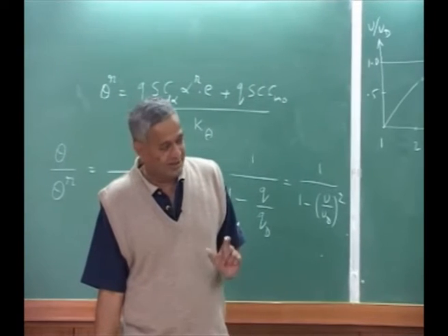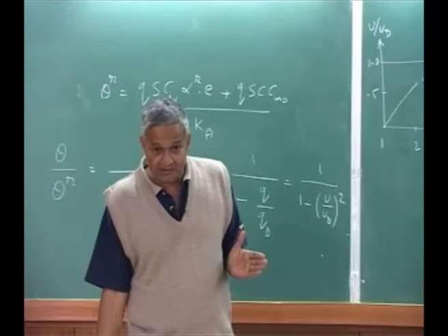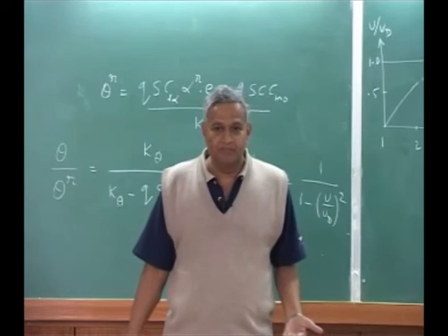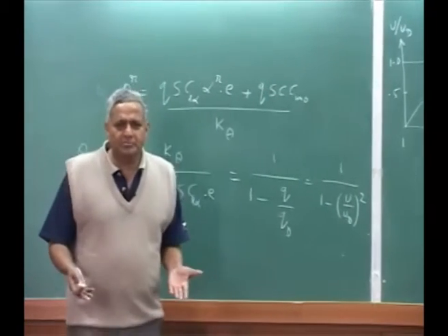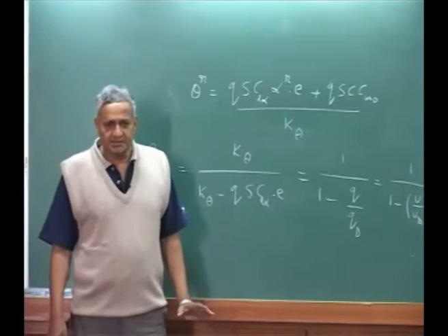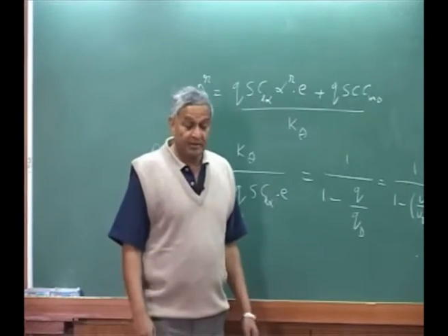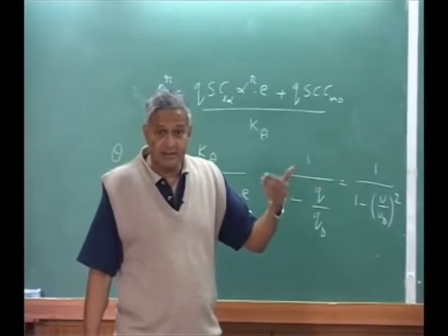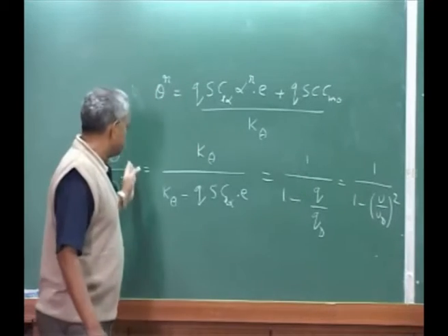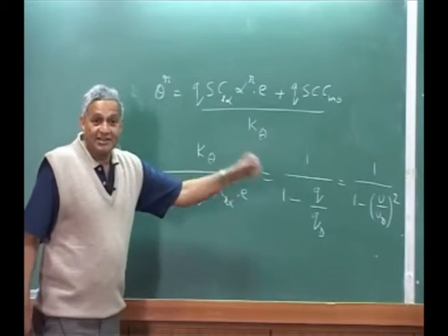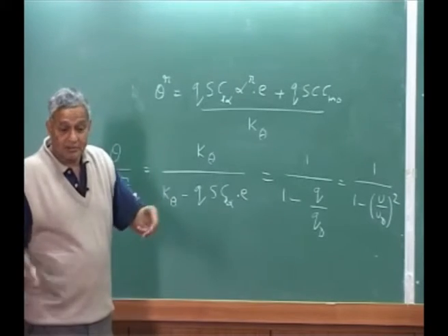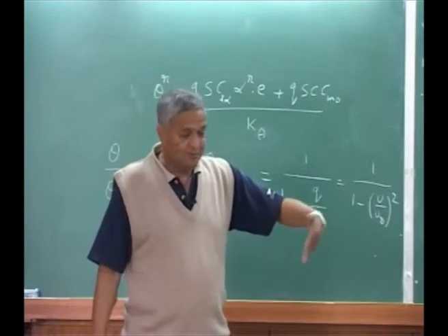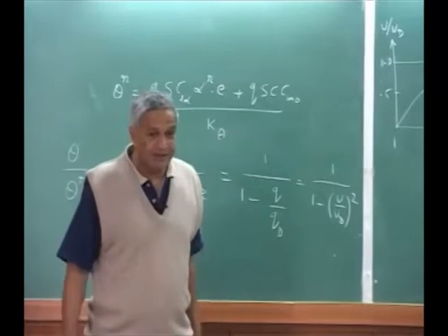That is why in aircraft structural analysis, initially in the preliminary design, you will not be bothered about elastic deformation and other things. You will make your design. But after that, you have to do an aeroelastic calculation to see whether the stresses are within the limit. Otherwise, even at half the divergence speed, you have about 30% increase in your twist. That is at the half. If it goes more, then it may be 2, 3, 4 times, and it may keep on going up.